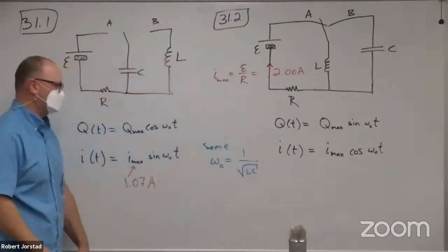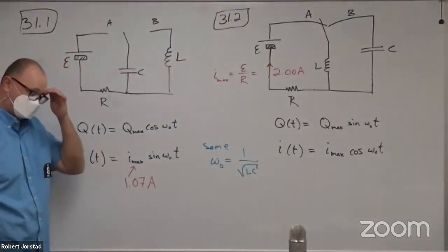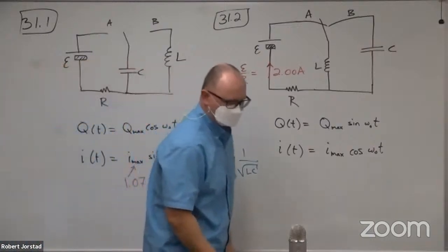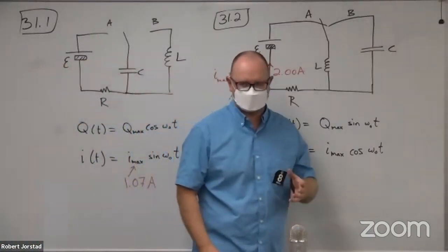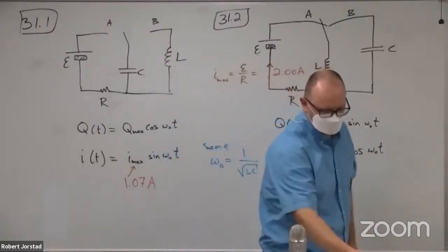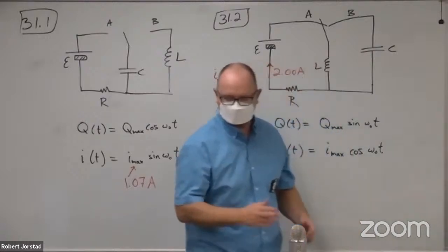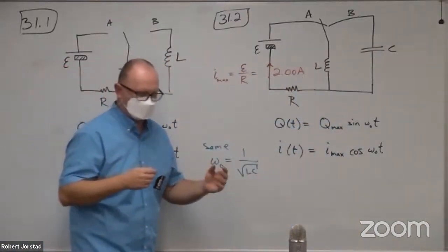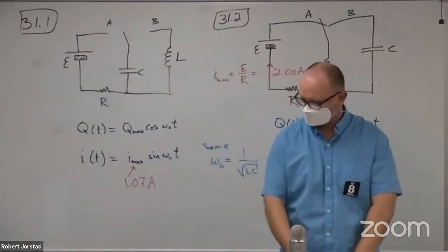It was always just kind of a fun lab, but this time we have a holiday, so we can't do it. So that's the way it worked out. If you want to build these, just look up Quaker Oats radio, buy or borrow the parts from me. The idea is you use a variable capacitor and variable inductor, and you can tune to different frequencies, different radio stations.